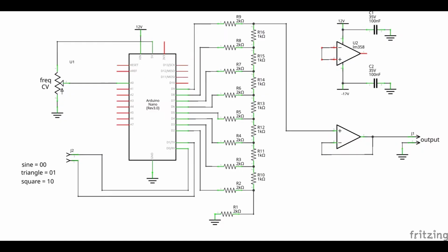And we could do that simply using multiple digital output pins rather than one, so we can define the various voltages we need as a binary number. And we can use these digits as the inputs of a digital-to-analog converter, like for example an R2R ladder. The output of the DAC should provide us with a particular wave shape associated with the samples we were using.